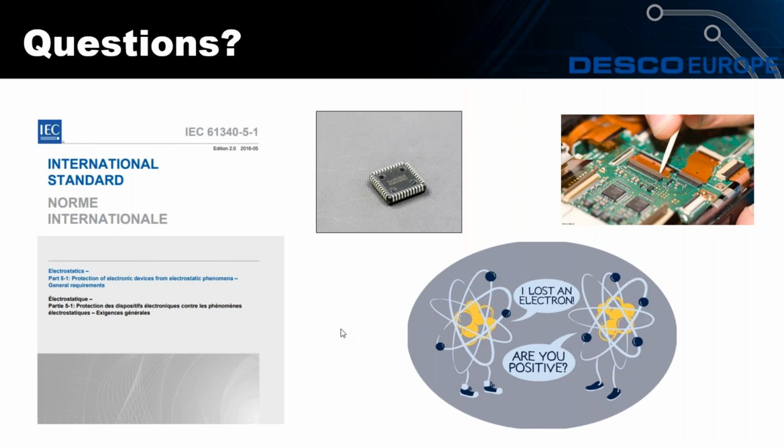It's performing two tests. One is the offset voltage or balance test to make sure that the ionizer is within balance, but also every 4 minutes or so, it's performing a decay time test. Now, it may be that when you switch an ionizer off, the environment stays in balance, but it will fail that decay time test if it's been switched off by the operator. So you will know if the ionizer that you spent money on has been switched off at the workbench if you employ that continuous monitoring solution.